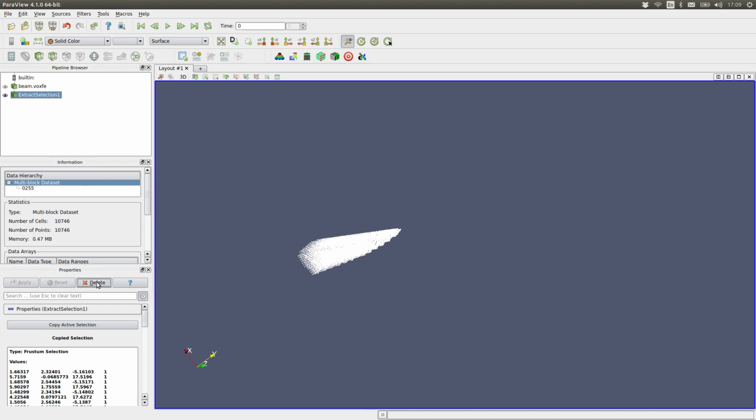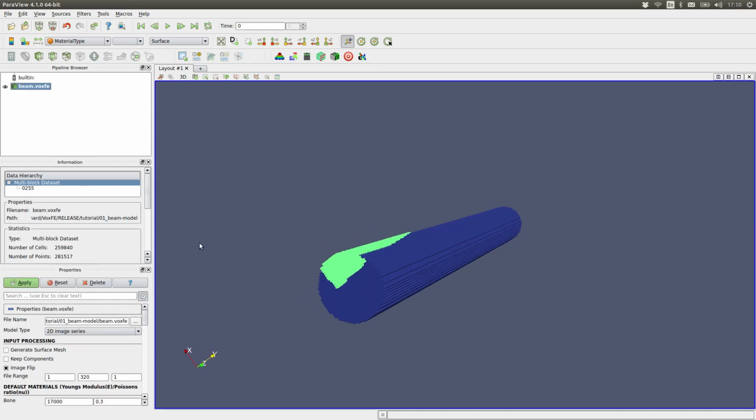If I get rid of that particular selection, supposing I didn't like it, something that's very useful to know is that I can create a selection by just selecting this button. You always have to come back and press this button. I can get rid of that by clicking outside the object. If I select this region and I click it again and press Control, that means it will add to the existing selection.